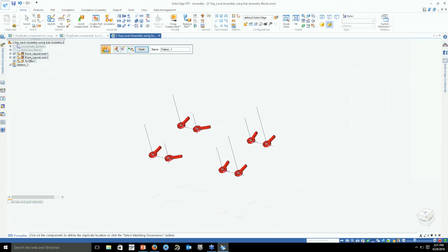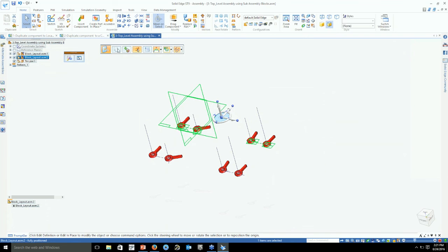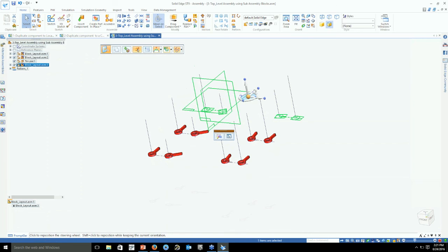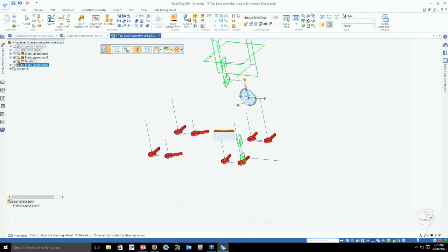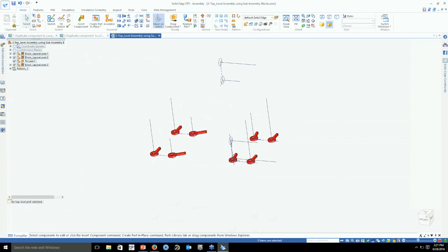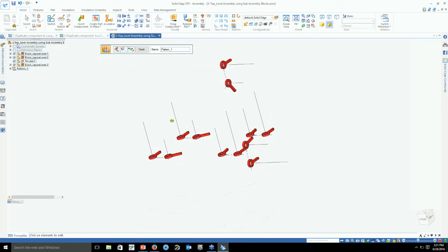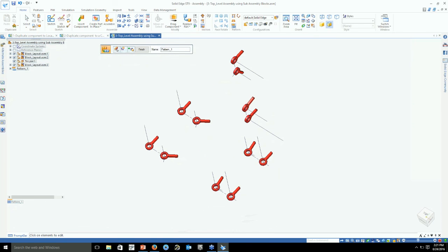And to go one extra step, this is just a real simple thing to do with the synchronous tool. Just want to go ahead and copy one of these subassemblies, and let's just drag it out here. And let's just rotate that around. There we go. And just again, go right back into my pattern, accept it, tell it where I want to go to. Go ahead and just grab that one now. It follows along, tell it to go to all of them, accept it, and there we have. So there's really not much faster way to get a part oriented any orientation you want just by a couple of 2D sketches and some subassemblies.